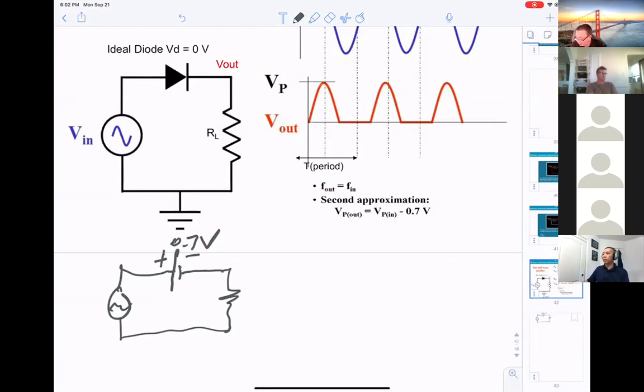Okay, so now, when you draw that, first thing is you say the diode is on. At the output here, Vout, you get two voltages, DC and AC. What does the DC voltage equal? 0.7. Half of the AC, based on the graph.